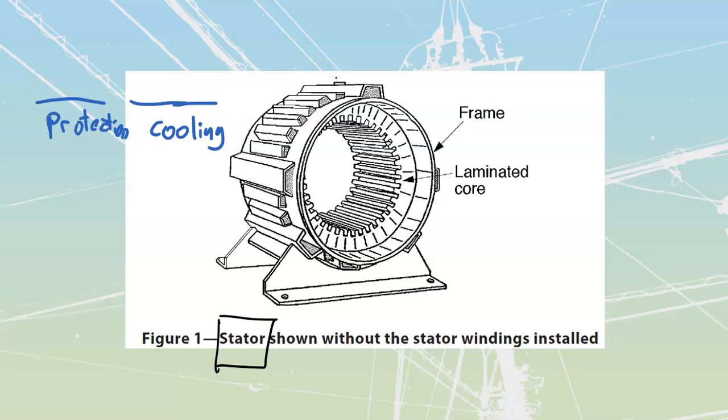The first one that they talk about is the drip-proof machine. Now, the first thing that we should talk about is that this thing is actually going to be called ODP, Open Drip-Proof Machine. It's one of our more common ones. All that it means is that the openings are going to be down low. The end bells are usually going to be sealed all the way across the top. So if any water drips onto it, it's going to run down past here, and then it's just going to drip away. It's not going to get inside of the motor itself.